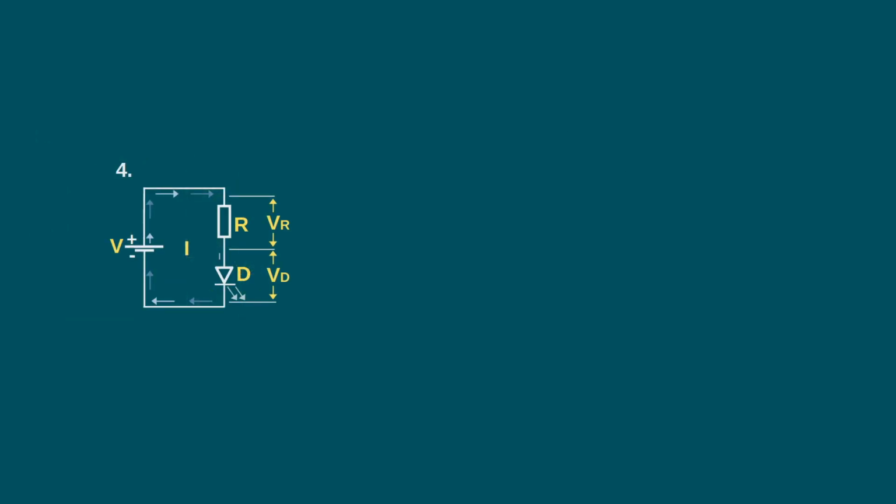The next is a series circuit with a signal LED, in series with a resistor, which shows the status of a device, power on, or if it does not light, power off. It is a mandatory part of various chargers, laboratory power supplies, and so on. You can find out all the parameters of the diode from the manufacturer, and based on that, calculate the value of the required resistor for different supply voltages.